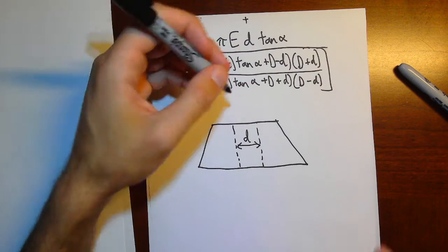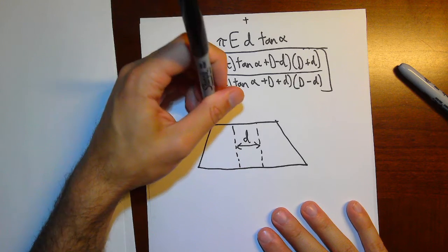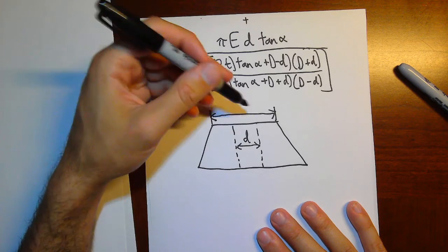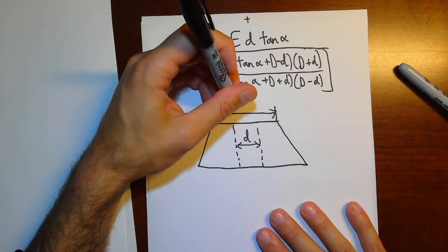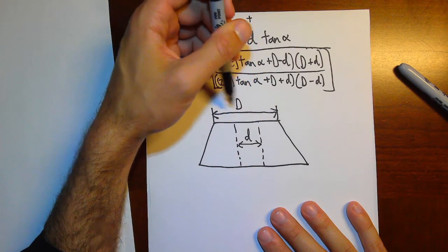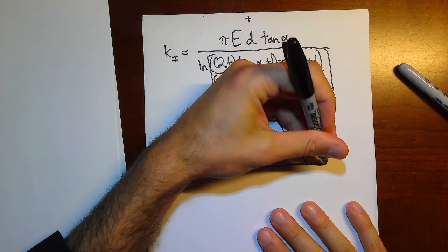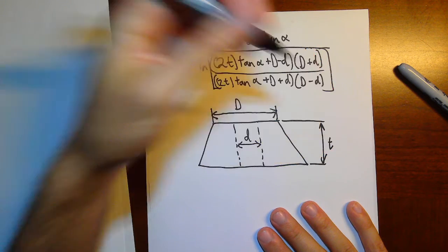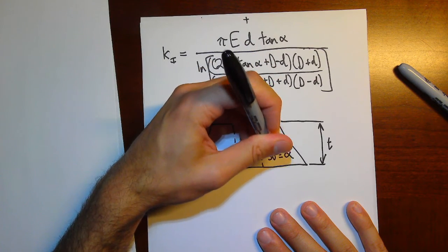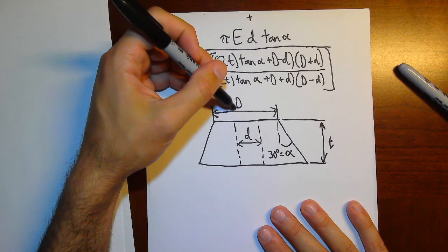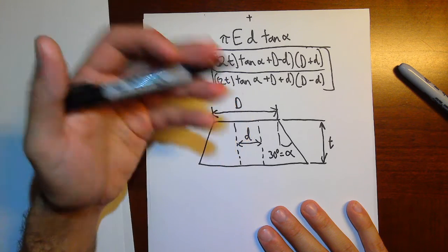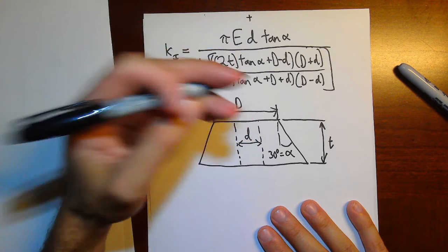Then we have the diameter of the top of the frustum, or the top is a misnomer. It's really just the smaller end of the frustum. That's cap D. That's one that we're going to have to be very careful of as we go through here. And we also have it in terms of the thickness, t, and the angle, alpha. Well, we already said that that's 30 degrees, so that's pretty straightforward. We just have to figure out what big D is. Small d, we know, is always the clearance hole size, because our hole is the same diameter the entire way through. Very key to note.